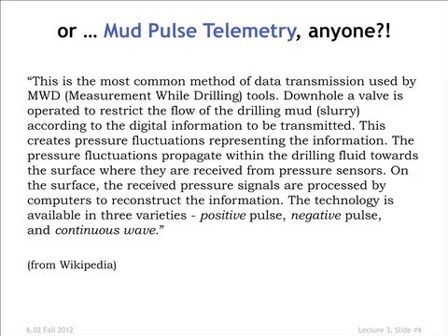Here's one you may not have thought about, mud pulse telemetry. So when you're drilling for oil, you'd like to get information from the drill bit at the bottom. And normal electronics doesn't work too well because the temperatures are fiercely hot down there. You need that information to help you steer the drill bit, to get information about what sort of rock you're going through and all of that. So they actually seriously do use pressure pulses in the slurry that's cooling the drill bit to try and convey information back to the top. So they'll modulate the pressure down at the end of the drill bit and hope that you can detect it at the top.